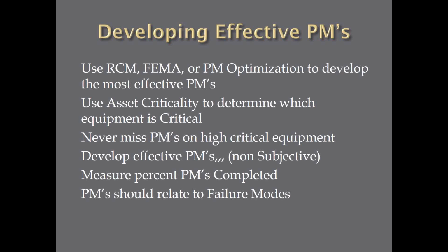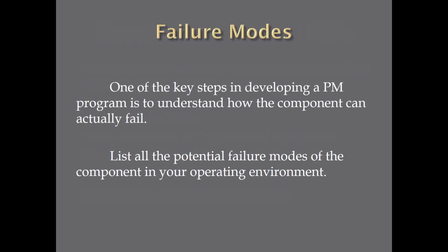PMs should be related to specific failure modes. So one of the key steps in developing a PM program is to understand how the component can actually fail. List all the potential failure modes of the component in your operating equipment. Again, one of the future webinars we're going to do this year is how to do an RCM analysis, how to cost effectively do that analysis to develop your maintenance strategy.